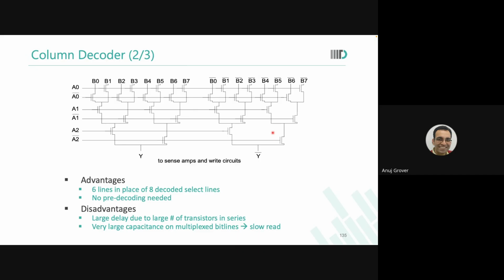When we get to the multiple stages of MUX, do we also have to use multiple sense amplifiers? Good question. Arpit is asking, if I was going to a 2-stage MUX, do I need to add 2 levels of sense amplifiers? Not needed. Once the sense amplifier has come, you have output available in 0 and 1. A sense amplifier will amplify whatever small differential from the bit line you get into a full swing. So once you put a sense amplifier, after that you can have digital logic. Are you able to see this? So you don't need 2 levels of sense amplifiers.